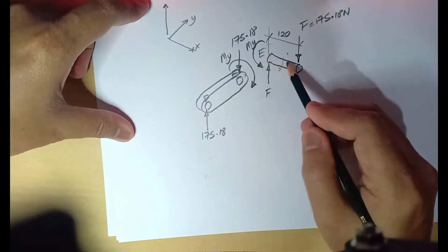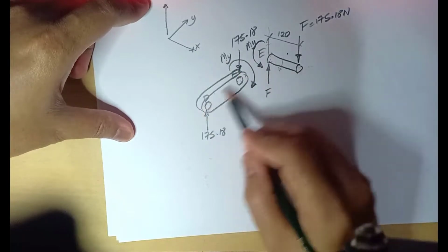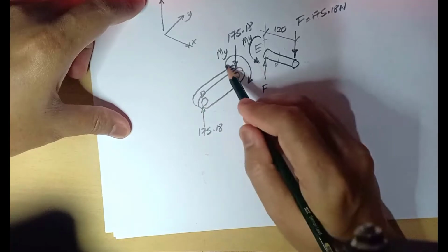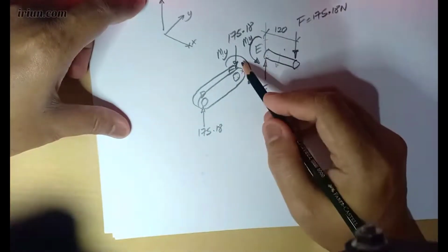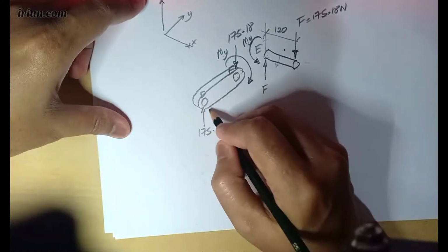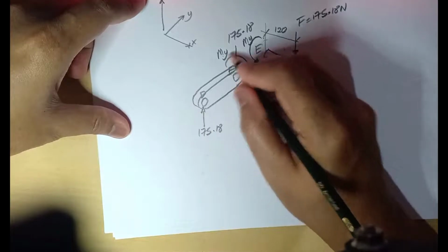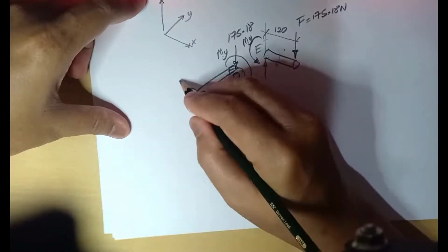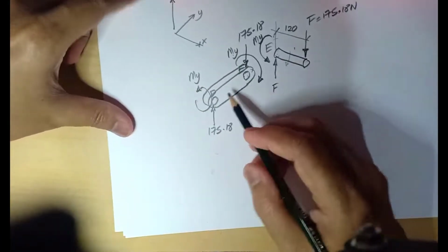At here it becomes bending by the same value, but in here the MY is the same, but it is more like twisting the member DE. So at the end, at D here it should counter react. Since this one goes for positive moment Y, and this one is clockwise, at D it should be counterclockwise MY, the same value. Right?